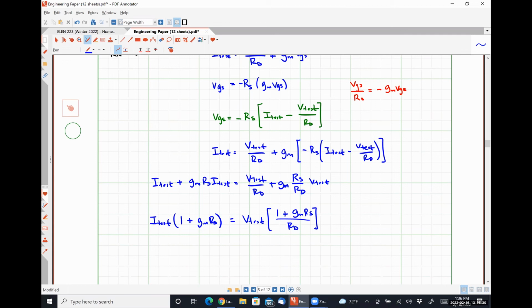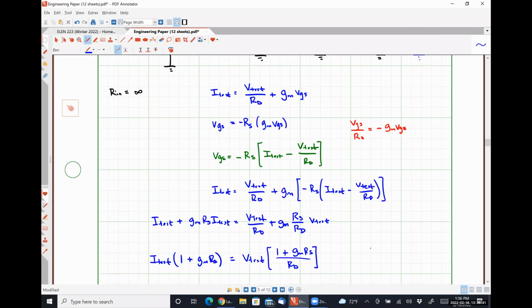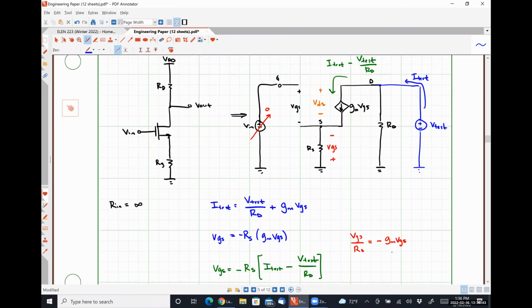Yes, what did I screw up, Jordan? So going back to setting it to 0, like I said earlier, think about it like the current source going in, separating everything else out. VGS goes from the bottom to the top of the resistor. If you have a positive current for VGS positive, you're forcing current through the resistor, right? That'll make VGS negative, right? Okay, so I see. So you're saying... quite possibly, yeah.